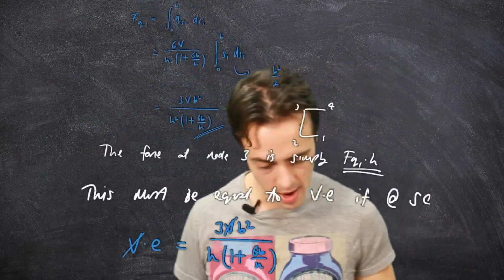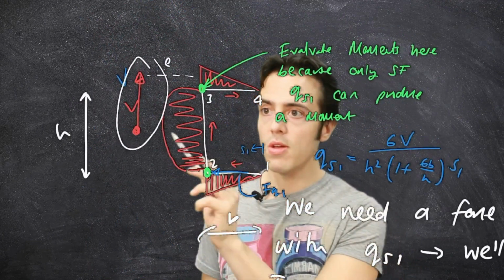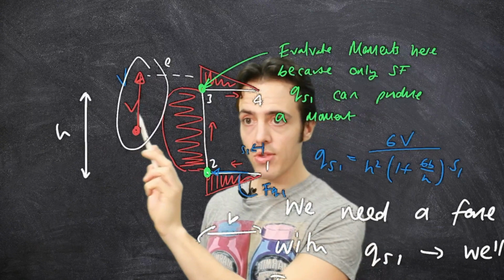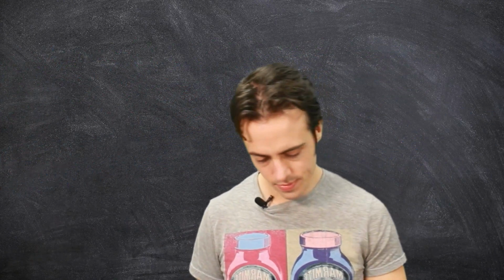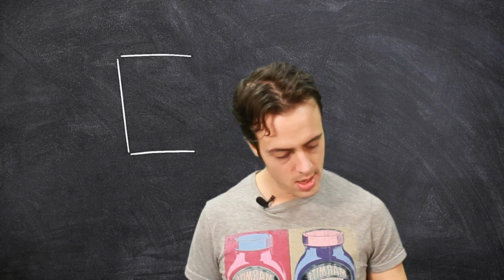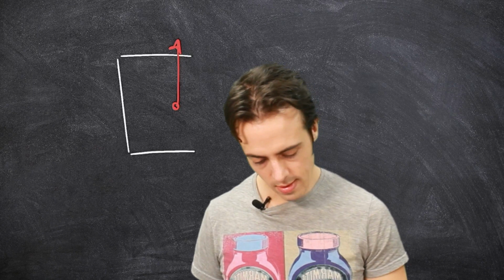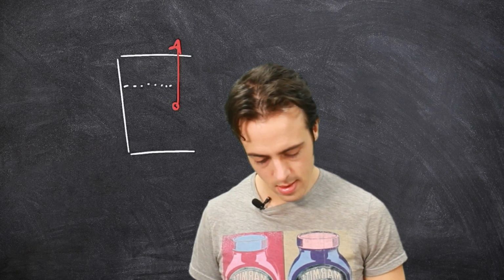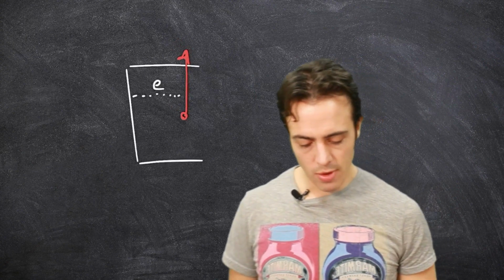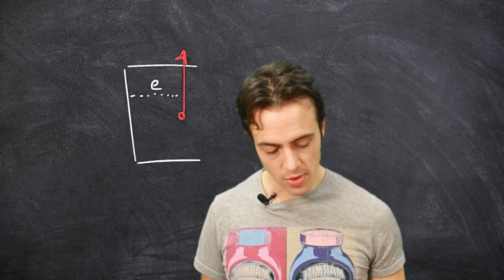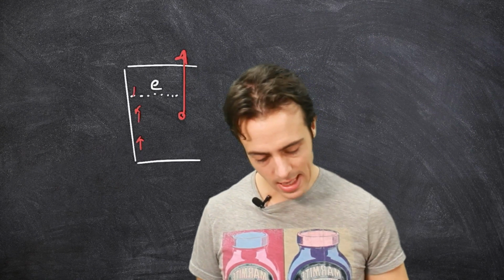Okay, and this was defined such that I gave this distance defined to the left of this centre. And if we'd done this differently, if we'd decided to load it here and called this distance E, for example, done the exact same thing, we would have found that we'd have to be careful with moments. So you would have remembered that the shear flow would be exactly the same.